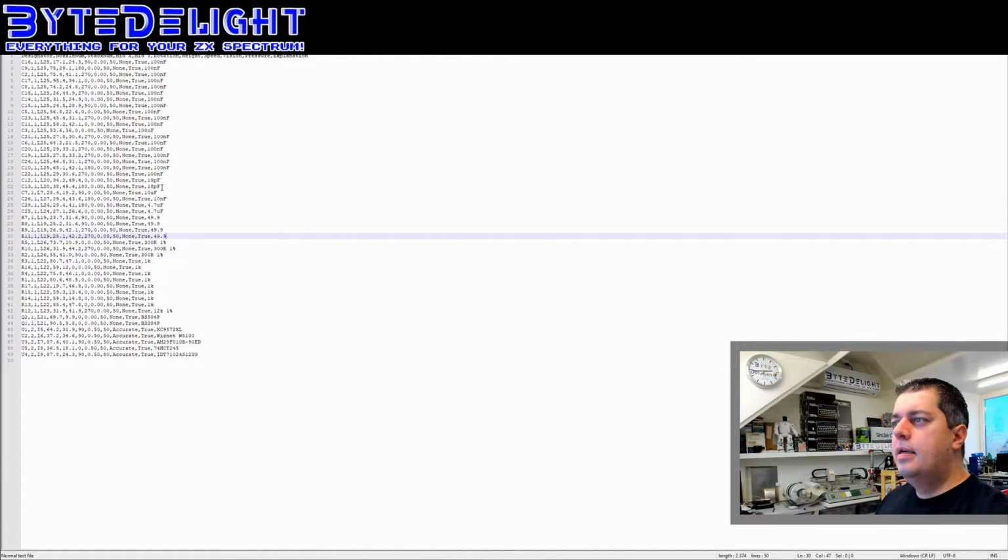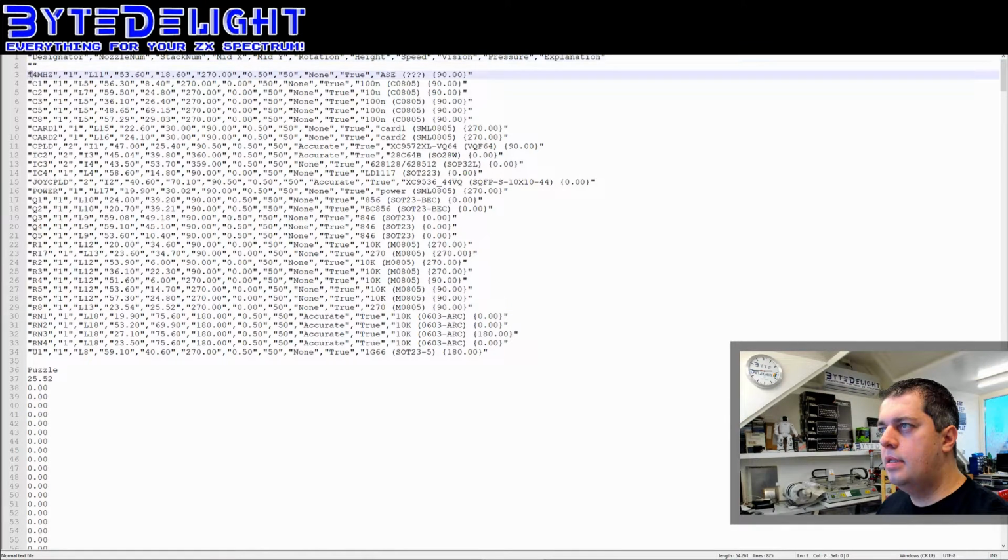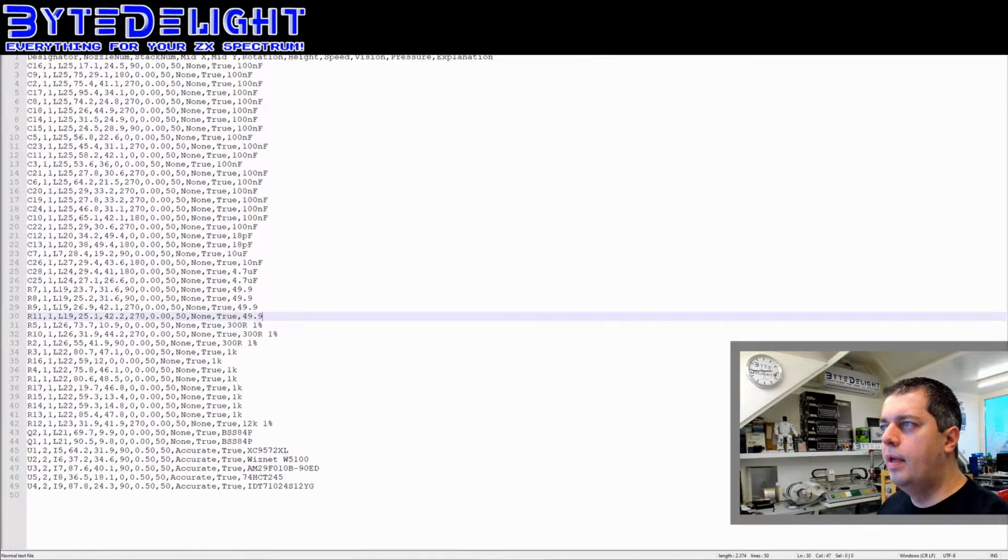So now comparing the two files, the new file we just made with the commas and the Pro1 file, the main difference I can see is that there are quotes around the values here, and I'm not sure if that will be a problem, so I will have to check that out. I know from experience that there is an option in Excel to add quotes to each value. I have to check that, but maybe it's not a problem. Maybe this format will be just fine with the pick and place machine software. So I have to check that. I have to read it in the machine.